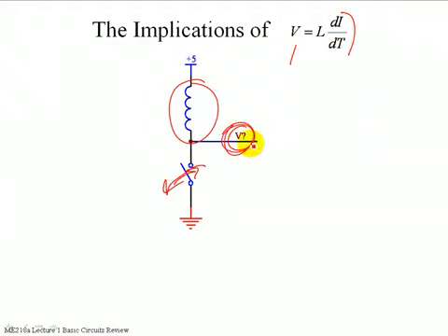This is going to become an issue because these voltages that it jumps up to are very easily hundreds of volts. They wear out mechanical switches. They can destroy semiconductor switches in just a matter of seconds. So the key thing to be aware of is this spike in voltage that happens whenever you try and turn the current off.